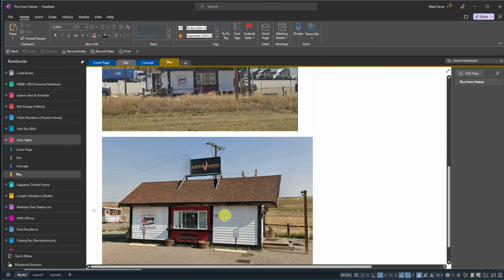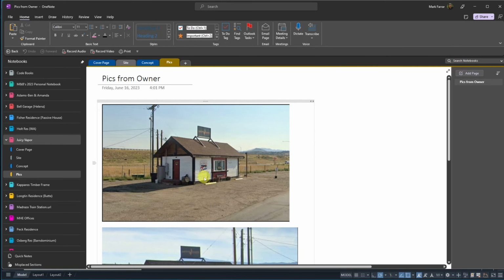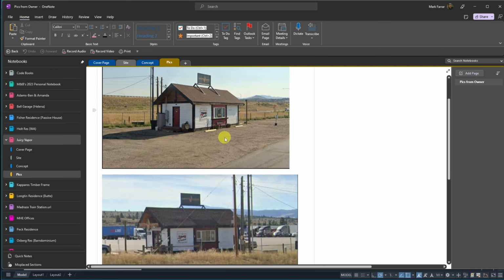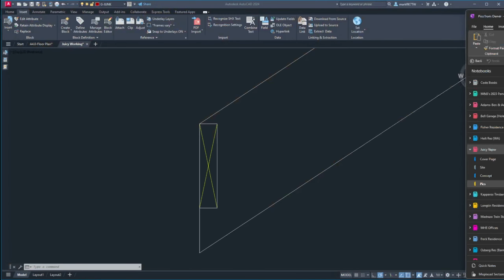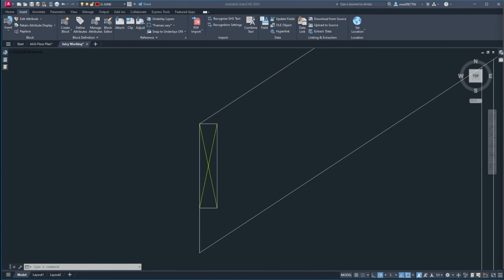So let's say this is 2x10, because if you look at the ends, they're at least a 2 by 10, I would say. So I'm going to go 2 by 10. And it's plumb cut. Looks like I have a king post here, and possibly that could be actually structural and not just visual. So let's kind of go with that assumption a little bit.